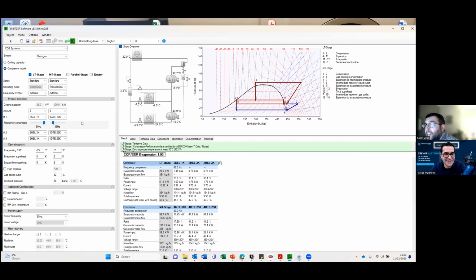Yeah, if we're to seek some sort of COP, as we state as an average, it's absolutely necessary to have it, because without that, what you suffer is a degradation coefficient from that cycling between two compressors involving start currents, transients, and all those effects which actually reduce COP. So if you actually want to hit that average COP, you need an inverter, you need a VFD.